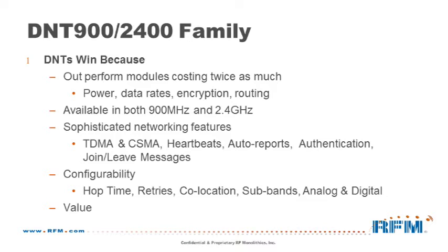We have heartbeats, where you can configure the radio to send a brief message saying that it's still part of the network. So that if a remote is only transmitting very infrequently, you can know more frequently that it's still there, and it's only not reporting because it hasn't asked to, as opposed to the fact that it's left the network. We talked about the auto reporting, which is a key feature, really simplifies monitoring and sensing applications.